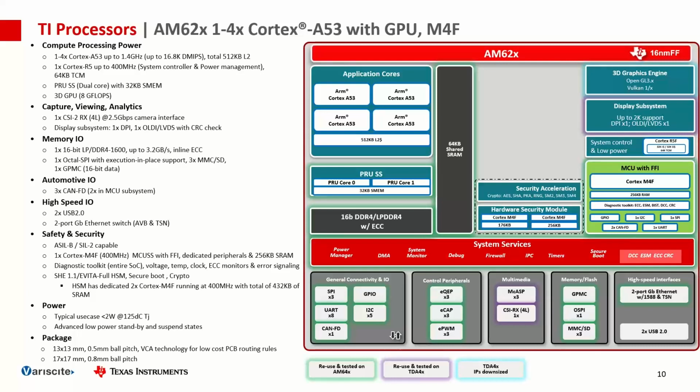That is what some people consider to be a flexible I/O, but it is a coprocessor that is focused on real-time I/O, and so commonly gets used for I2C, SPI, McASP, which is our equivalent to the I2S protocol, and then on the networking devices, Gigabit Ethernet comes out of the PRU as well. So a lot of features get opened up by having those flexible I/Os.